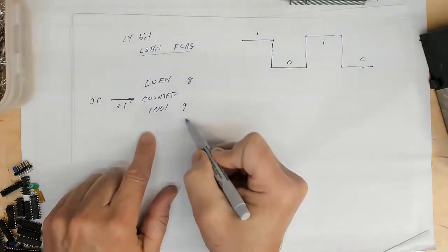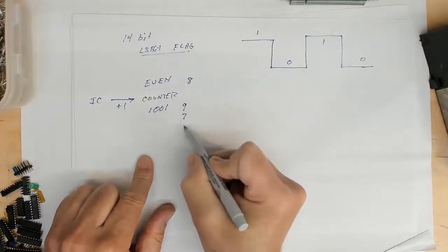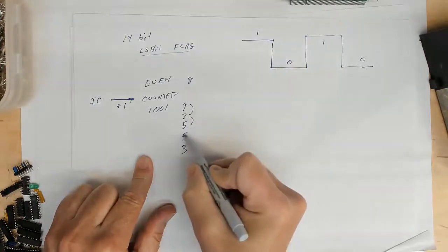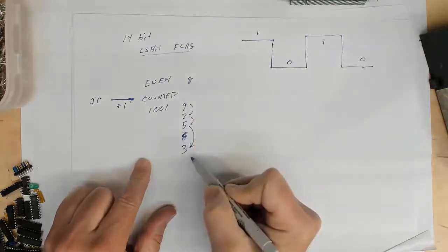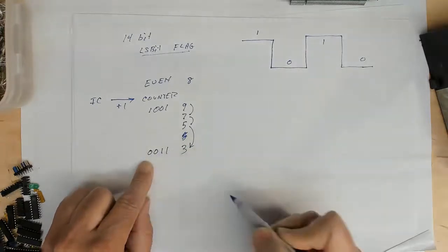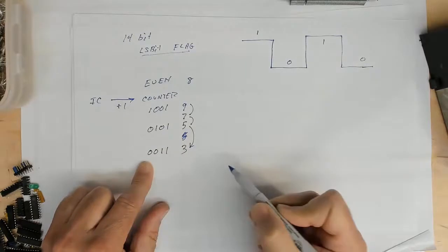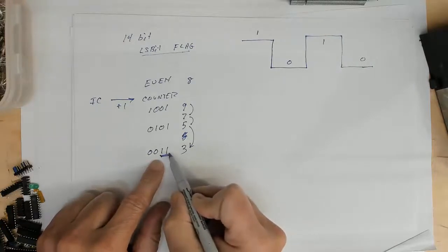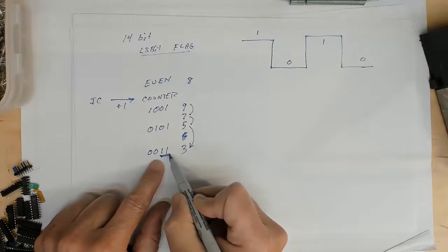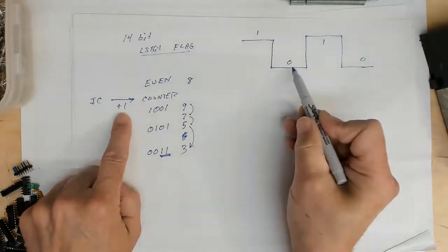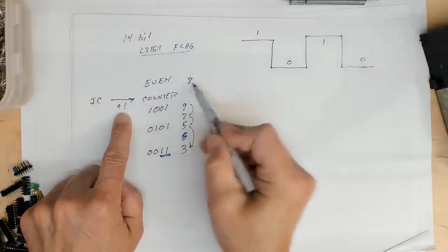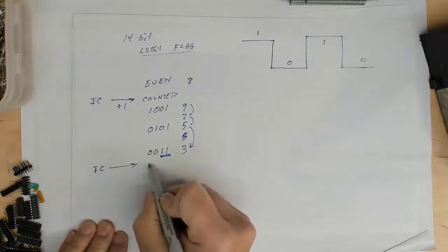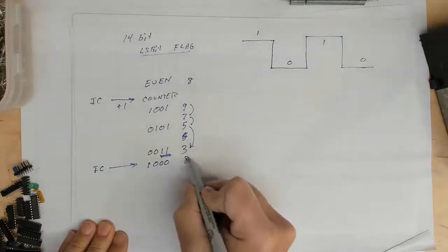Now this will decrement by 2. So it'll go 9, 7, 5, 3, so decrementing by 2. Let's look at this 3, that's 0, 0, 1, 1. 5 was 0, 1, 0, 1. 3 is actually the terminal count. So as it turns out, at 3 they have to stop and reload the value. But this time when they reload, they don't add 1 to it, because now we want the least significant bit to be 0. Since this was an even number, the least significant bit was already 0. So now they just take whatever was in the initial count and reload that back into the counter as 1, 0, 0, 0, which was our 8 again.